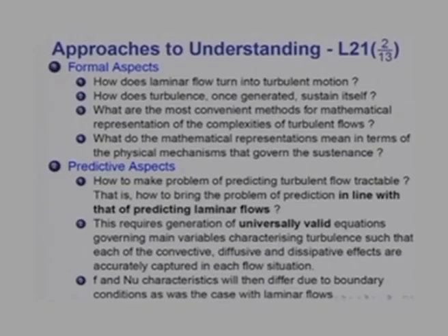After all, if the Reynolds number was greater than 3000, let us say 10,000 or so, or 1 lakh or 1 million, whatever, the flow becomes turbulent right from the entry to the tube and remains turbulent right to the exit from the tube. And this has been evidenced in all practically encountered lengths of pipes, of whatever diameter. For all practical lengths of pipes, it has always been observed that a turbulent flow, once it is turbulent at entry, always remains turbulent right through, that is, along the length.